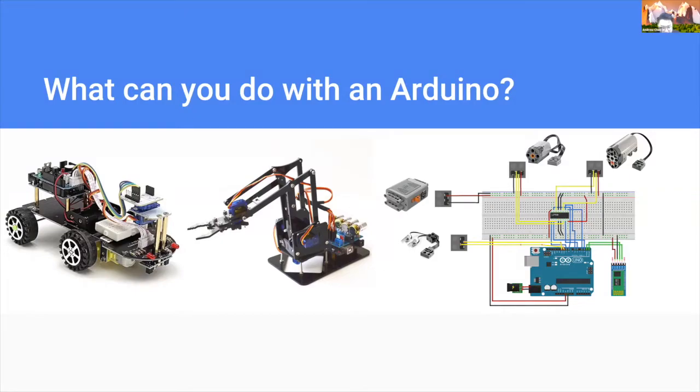The same thing applies to the servo motors at the very front, the one that controls the claw and the one that controls the main motion of the arm. These are not Arduino servo motors. These are just a third-party servo motor that you can control. A three-pin servo motor you can connect to the Arduino board itself so that you can control them.